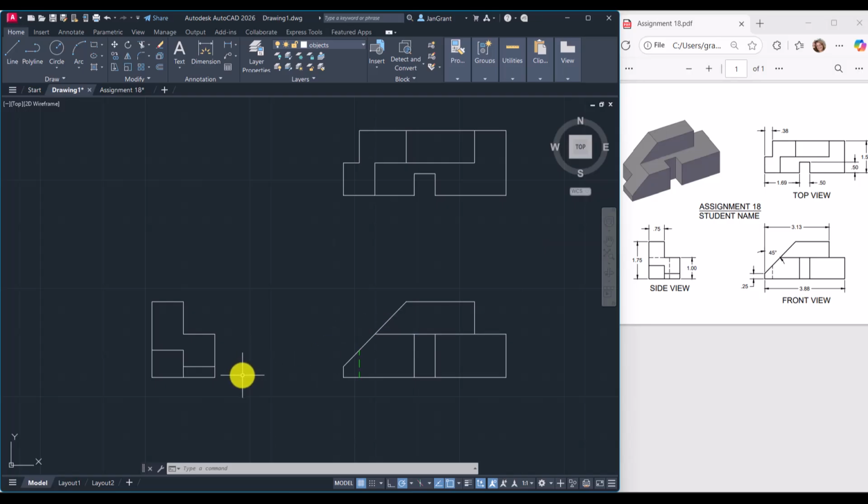All right, now this is a little bit different. You could set up the miter method angle and get this, but we already have the dimension. We already know that this notch is coming back 0.5. So let's just offset this line over 0.5. That's what that hidden line is.